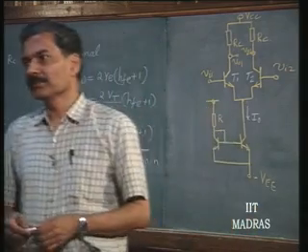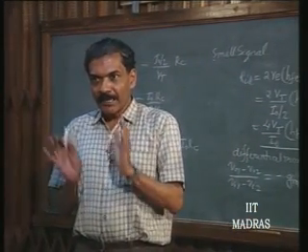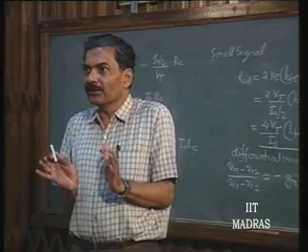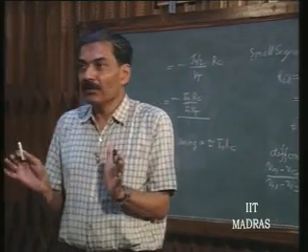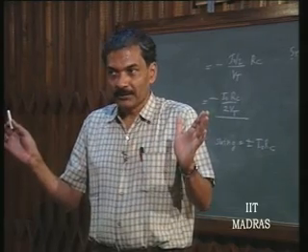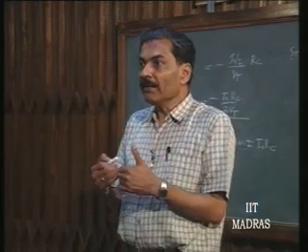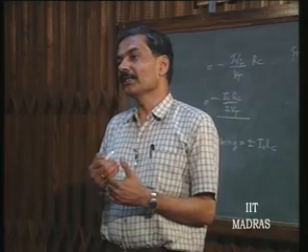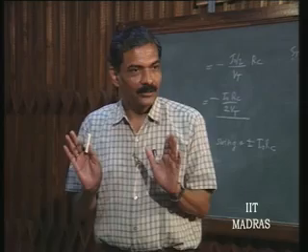Or VCC, whichever is lower. No, that is what I am telling. As long as the transistors are not going to saturation, it is independent of supply voltage. The supply voltage question comes into the picture only when limitation occurs because the transistors are going to saturation. Is this clear? Okay.